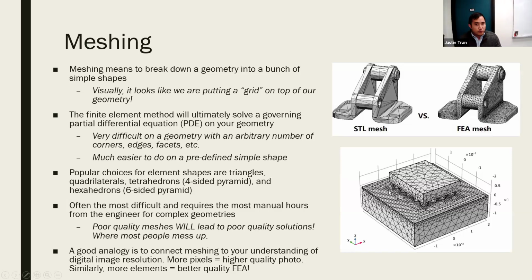And what you choose for the mesh, or how you measure geometry, is probably the single most important factor that's going to determine the quality of your simulation. Okay. So we're going to be spending a lot of time on meshing in terms of how we actually do this, what the best practices are, and what factors of the mesh affect your results. So meshing is something that's going to be really, really important.